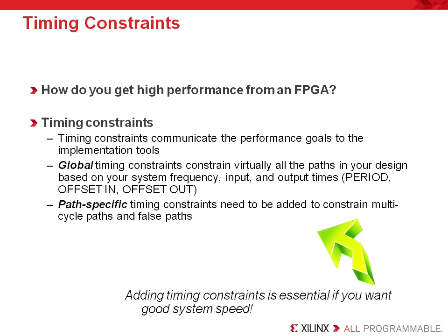Timing constraints are added by designers with their synthesis tool or with the Xilinx constraints editor. They are the primary means of communicating your performance objectives with the implementation tools. With timing constraints, the tools try to manipulate the placement of logic so that a routing solution can be found that meets all of your timing needs. This is simply not possible by hand, and controlling the layout of the design is much harder and requires more effort than you might think.